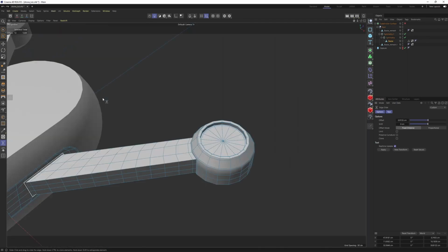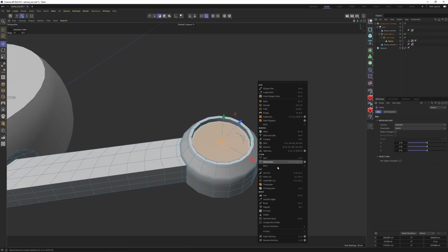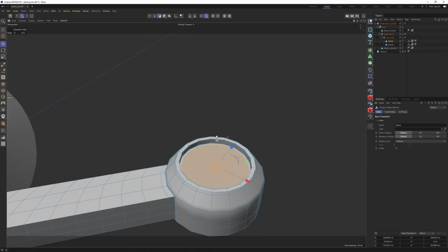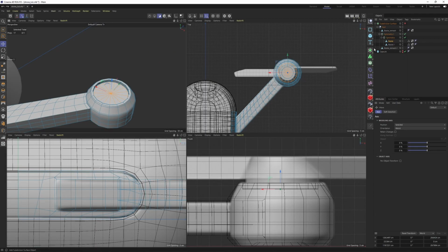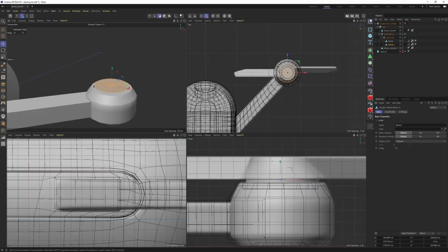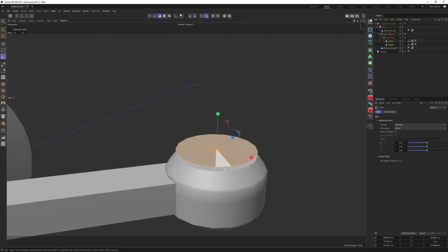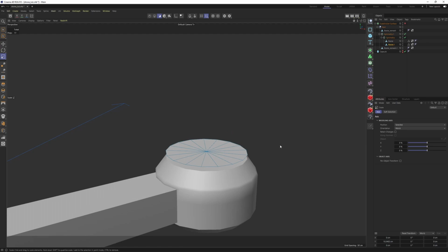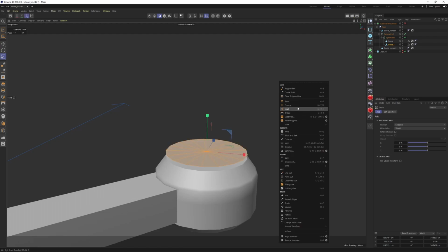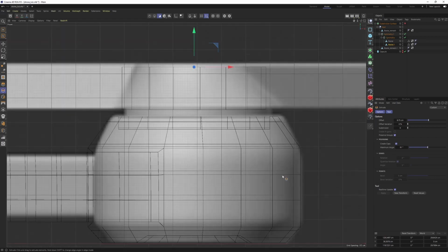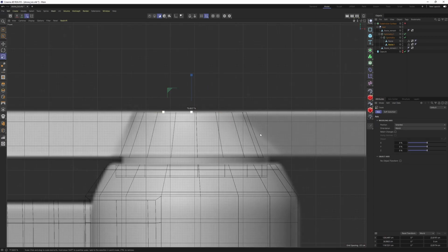Now let's check the blades. I will select these, and as usual, I will split them, move them up. We should select the split part, move these up. Then let's see from the top view, I need to scale them just a bit. Then we will need thickness, of course, and I'm going to do that with the extrude tool. Grab that, extrude to over here, then scale them. I believe this part should be slightly larger, like that.